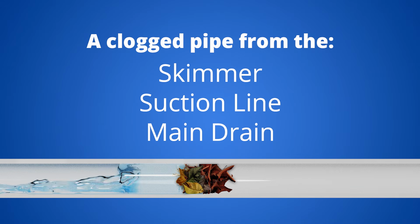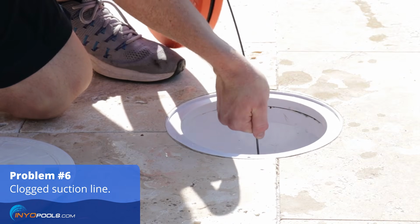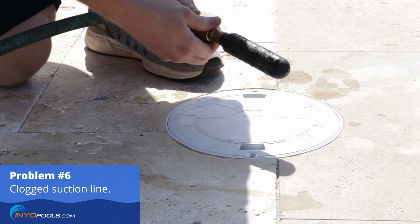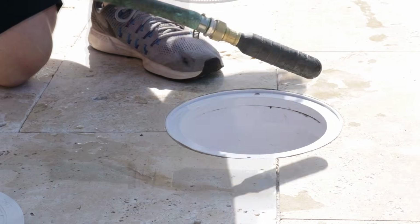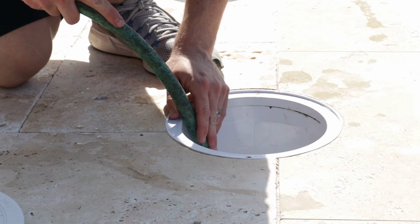Another cause of low water pressure could be a clogged line. A clogged pipe from the skimmer, suction line, or main drain reduces the amount of water to the pump. To free a clogged line, try feeding a fish tape through the plumbing to dislodge any debris. Another helpful tool used for this application is a plumbing bladder. Simply hook up a garden hose to the bladder and slide it into the skimmer or suction line. Turn on the water and the bladder will expand and blow out the lines.